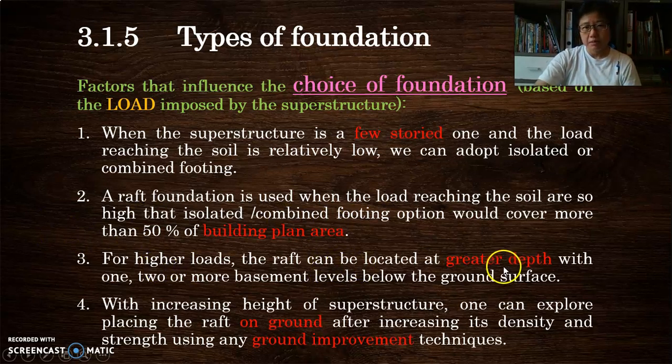Alright, and if the loads are greater, then you may be looking at putting your raft at a greater depth. Remember the effective depth that we talked about. The deeper you put a foundation in, the greater the soil bearing capacity will be. Logically, the deeper it is, the soil layer would have sustained a bigger load because of its own self-weight and the layers on top of it pressing down. So that will give it a better bearing capacity. The challenge is that you have to dig deeper, and a deeper excavation site will need more support, and there's always a risk of collapse of your excavation site.